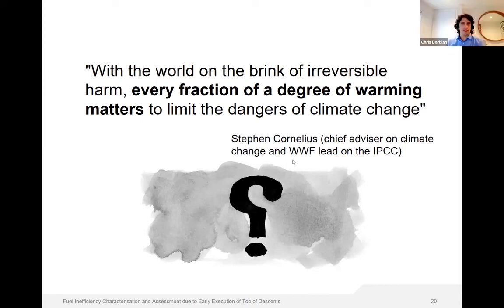Yeah, it makes sense. Another question from the audience, a little bit lengthy. Would your methodology capture the early descent in published procedures? For example, in CDO procedures, early descent is often flown in a managed mode with idle thrust, and is then followed by either a level-off segment or a segment of thrust descent until intercepting the optimal profile after the published constraint has been met. This is a suggestion potentially for follow-up research, if that's not something that has been taken into account yet.